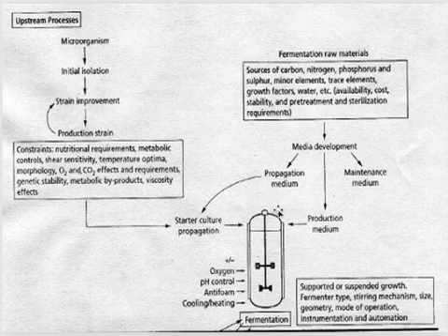Okay, so you prepared your starter culture, you prepared your production media. Now you put everything in the fermenter. Will you just put them in the fermenter? No. Before doing that, you have to prepare your fermenter. You have to clean the fermenter properly. You have to sterilize it. Then you will put the starter culture and the sterile production media into it, and you will do your fermentation.